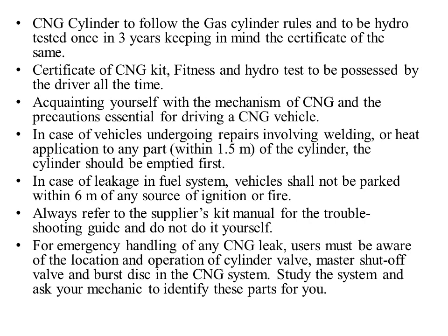And the CNG cylinder has to follow the gas cylinder rules and be hydro tested once every 3 years, keeping the certificate of the same. That means a thorough testing has to be done periodically, and the testing they do is hydro testing. The certificate of the CNG kit, fitness test, and also the hydro test has to be kept by the driver all the time. One should acquire the know-how of the working mechanism of CNG, and the precautions to be taken while driving a CNG vehicle.